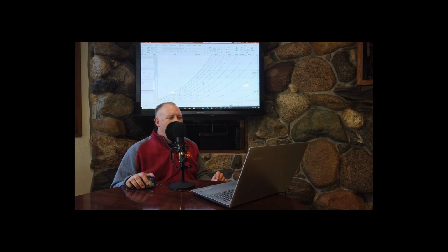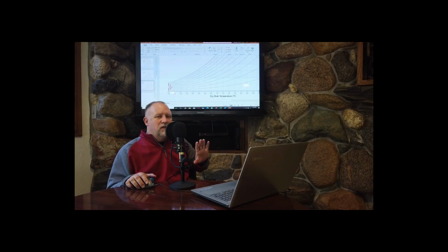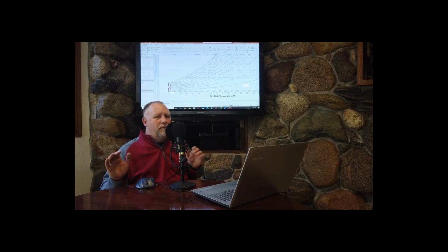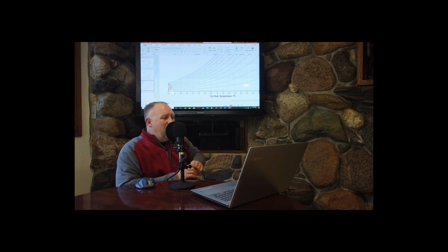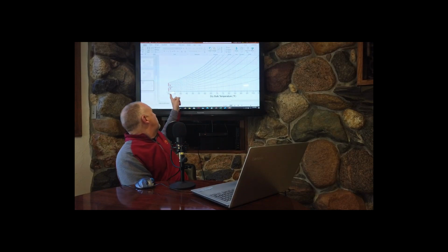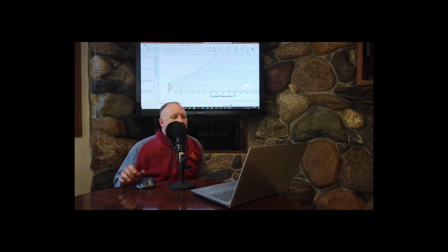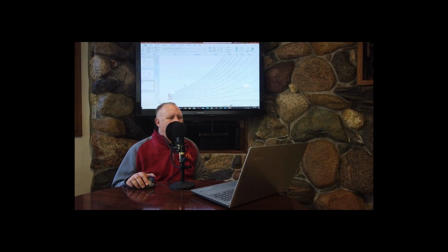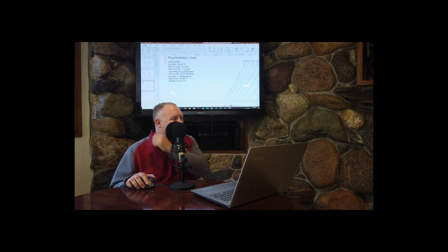All right, let's go to one more example. This one I did at the end of this Psych Chart. Yours, if you download the big one from the Canvas page, goes even colder, but I just took it to 30 degrees, 50% relative humidity. It's not that cold. 30 degrees, 50% relative humidity gives you a dew point of 14.5.